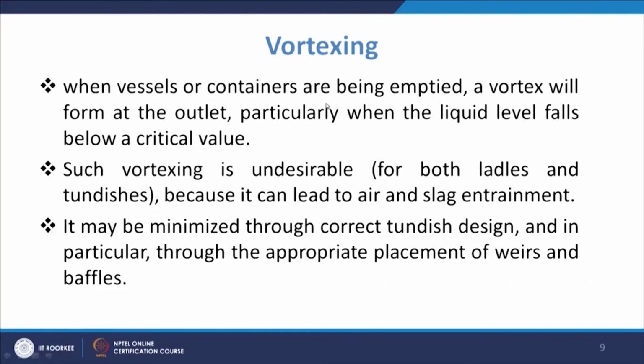Once it goes inside, there is likely to be slag inclusions, or there may be oxidation and formation of inclusions, oxidation of the melt also. So, basically you will have to see that this vortexing is avoided.